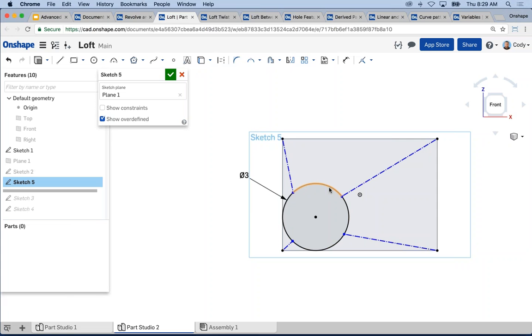And that's really the thing to stress: this is kind of the first line of defense when we talk about creating a loft transition that you want, right? Controlling that transition. Now, first attempt is always going to give you a little bit more twist. Well, I shouldn't say always, but many times you're going to get twists that you may not necessarily want. This is one of the first things you can do to correct it.